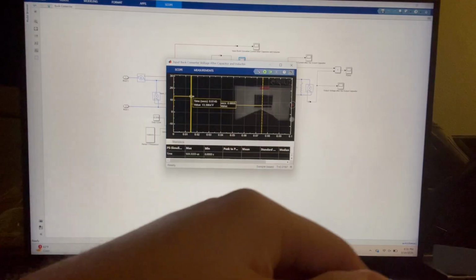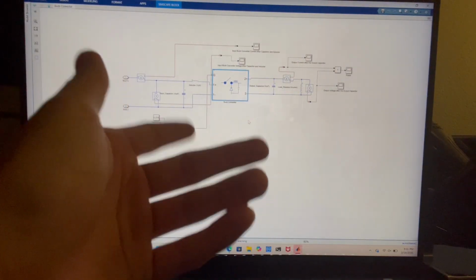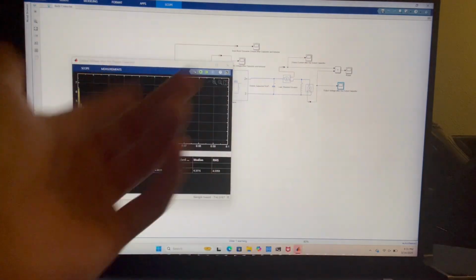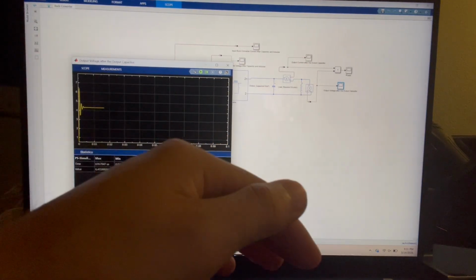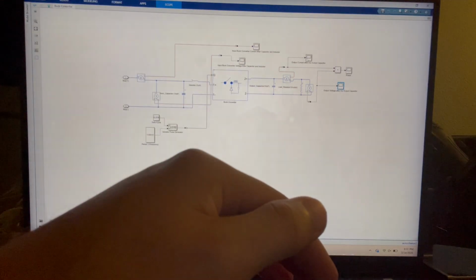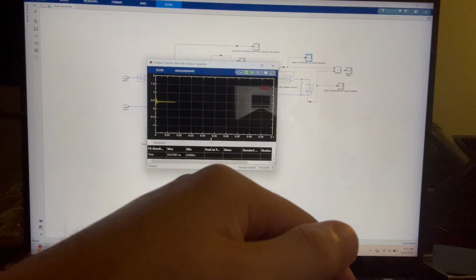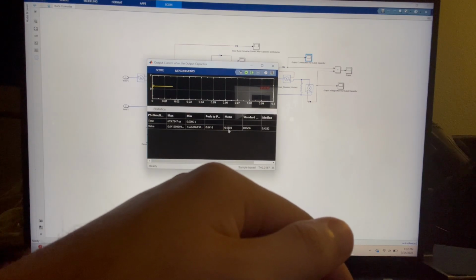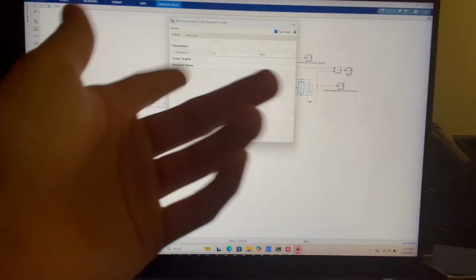It's about 13 volts. But as we did the math for a buck converter, our output is actually 4 volts. We can filter this. This is just the filter. We actually have about 4 volts mean. Current, we have 0.5, or 500 milliamps, 0.6, going to our load, which is a good amount with a load resistor of 10 ohms.